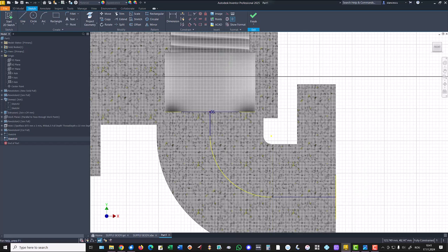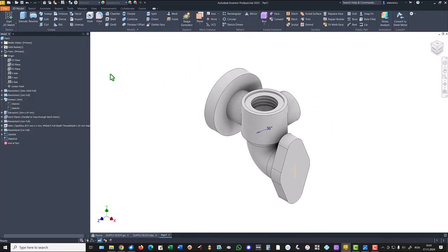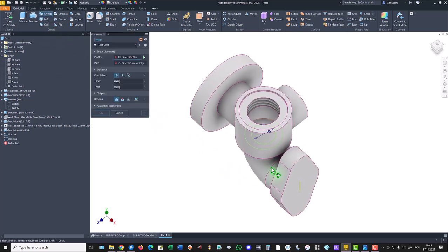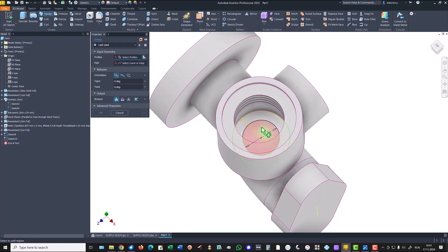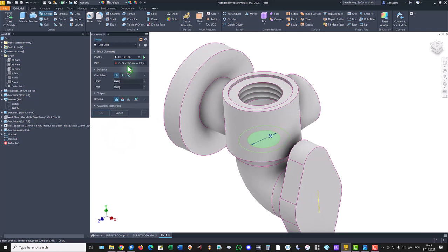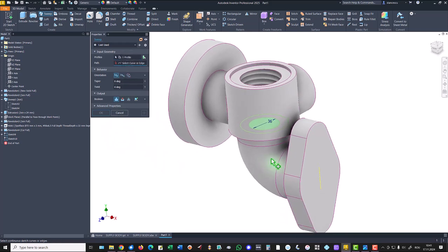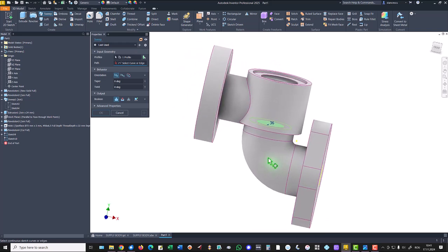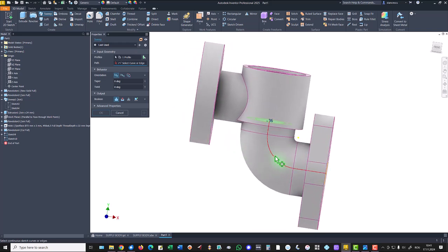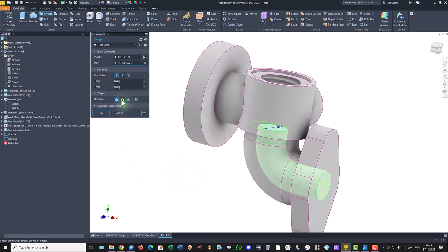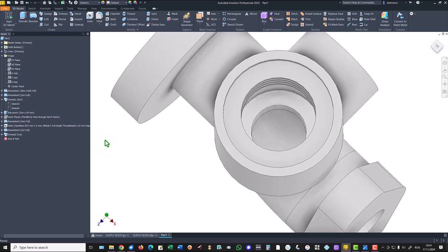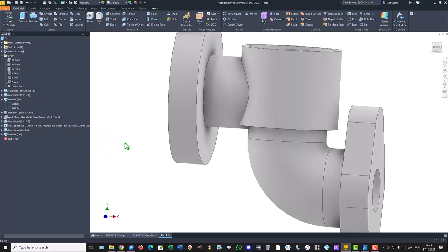As you can see, finish sketch, sweep. We have to select what circle to be used, this one, and we go to the curve. The curve is inside this one with cut. Okay, you see the result.